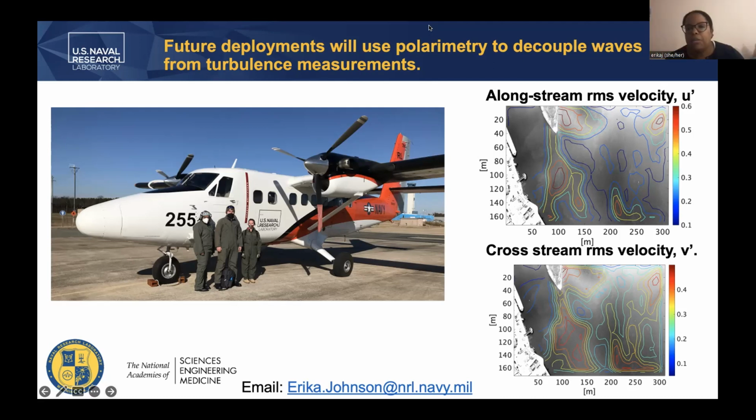That is something that I am currently looking at. Certainly, I have a PIV type code embedded in this one. I'm basically doing both at the same time, so I can look and compare. It definitely does show up. And the way that I would handle that is, you can't necessarily use the dispersion relationship if you have something advecting through, but I can flag those sub windows and say, for these sub windows, we've got a lot of stuff advecting through. Let's switch to the PIV version and then map those two out together. Yeah, okay, thank you.